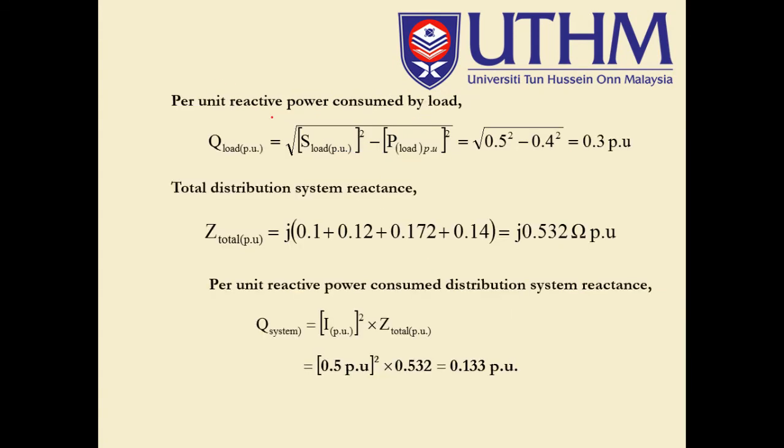And the per unit reactive power consumed by the load, so Q load is equal to the square root of S load PU squared minus P load PU squared. This is from the power triangle. Let me draw the power triangle for you.